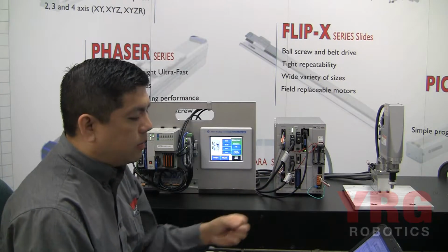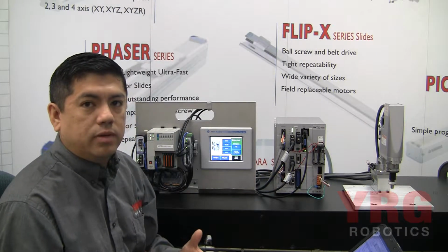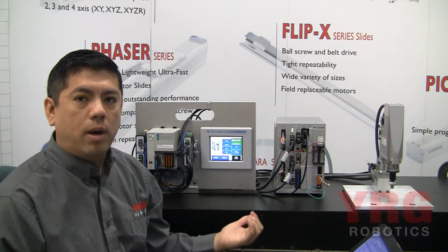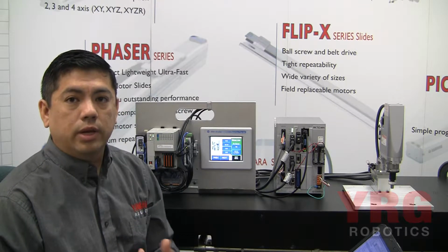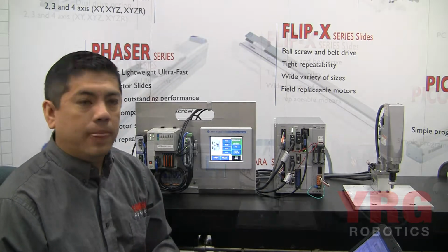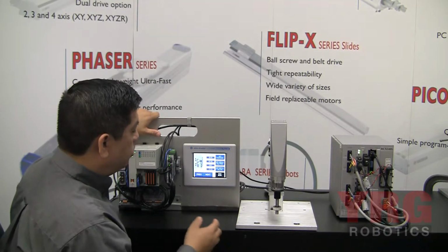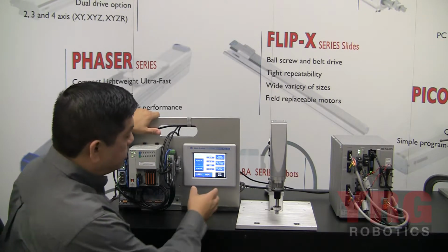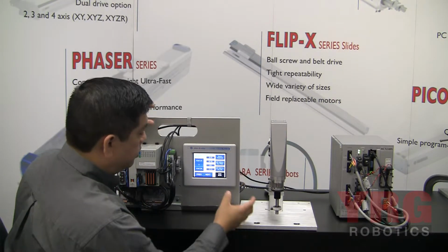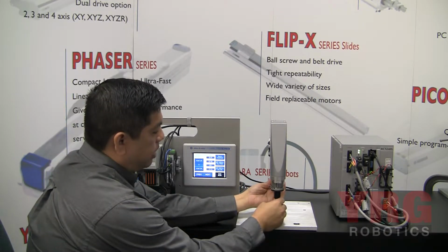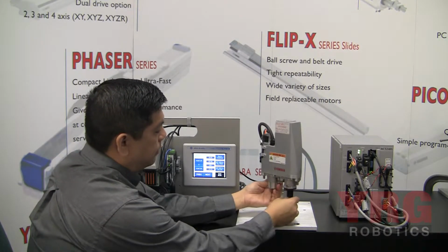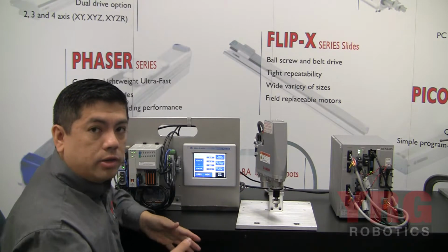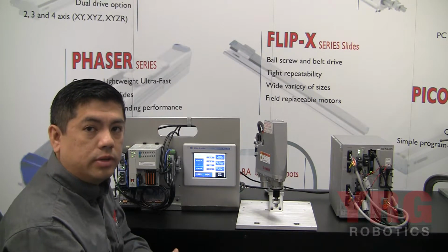Okay, so that gives us a great deal of flexibility. Rather than storing the points in the robot controller, we can actually create points in our PLC. I've got a screen set up here where I can do remote teaching of our robot. And I'm going to turn the servo motors off on our little SCARA. Now that allows us to move it by hand freely.